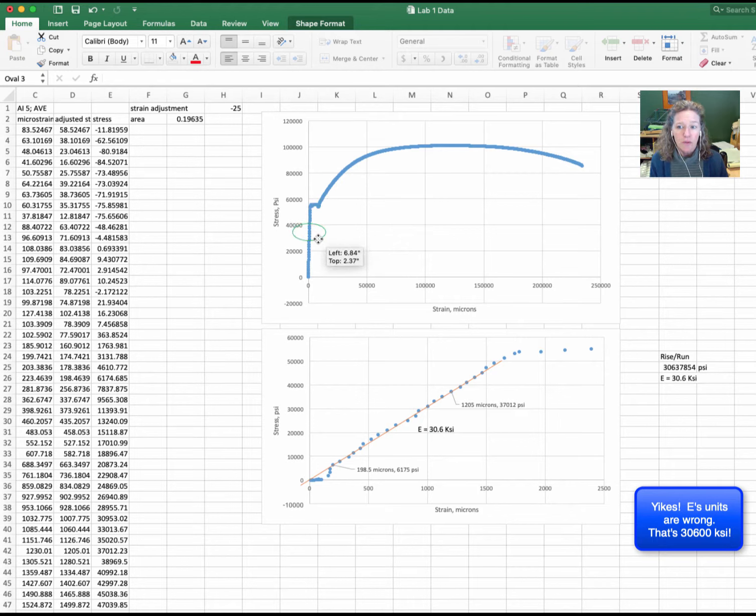And in fact, we are going to need to know the yield stress, the ultimate stress, and then also what is the slope of this line here, E. Now, one of the easiest ways to figure that out is to do a zoomed in plot. Then as we look at this zoomed in plot, we can draw a line across that plot, and when drawing that line, figure out what the slope is. So we can draw this line and figure out places that it crosses and simply do a rise over run from 2 data points.